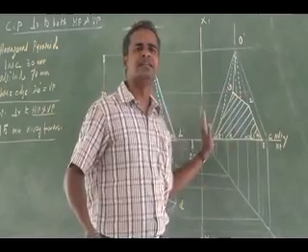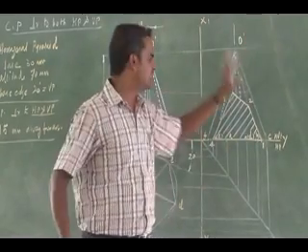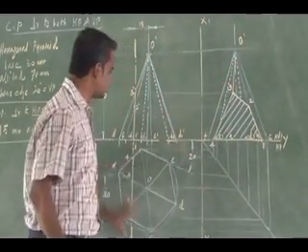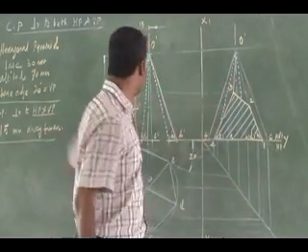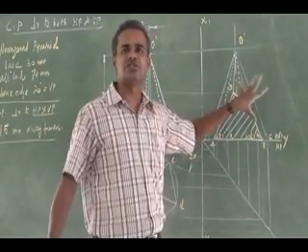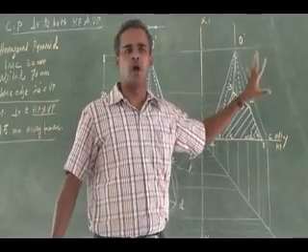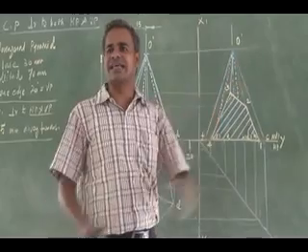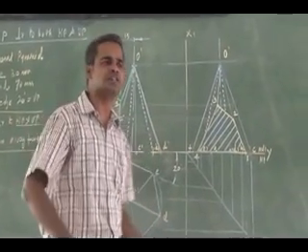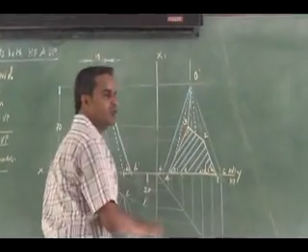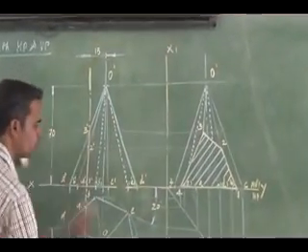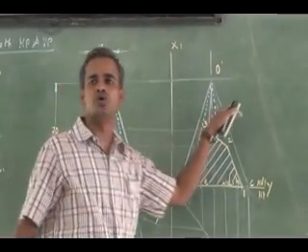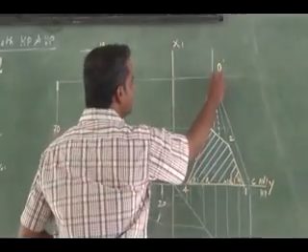I don't need to draw the side view, right? I can eliminate the side view. I can just project these cutting points to the 45-degree line, and horizontally I can project it. I can just show the true shape alone, right? Now it is asked, draw the sectional side view. So the sectional side view holds the true shape. After removing this portion, the remaining portion of the side view you should also darken. The remaining solid is this.